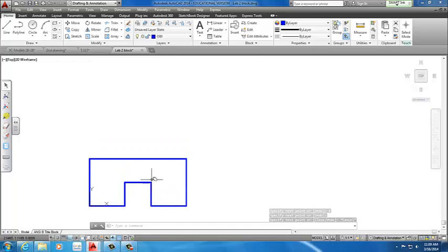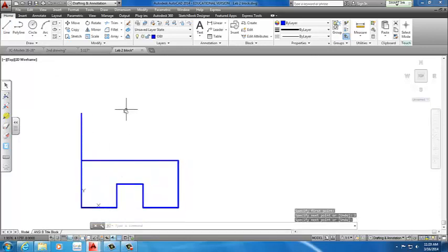Next step will be to create my top view. What we always recommend in this engineering drawing is to have the top view aligned with the front view, moving to the right. To do that, I just draw a line from one of these endpoints, about a distance of 2.14. So now that will be my spacing from my front view to my top view.